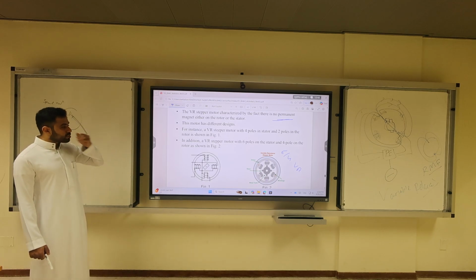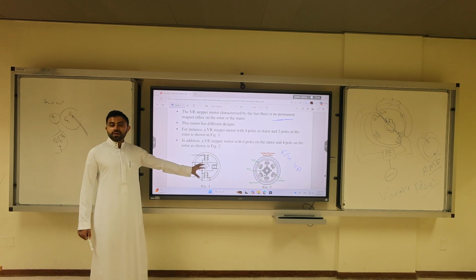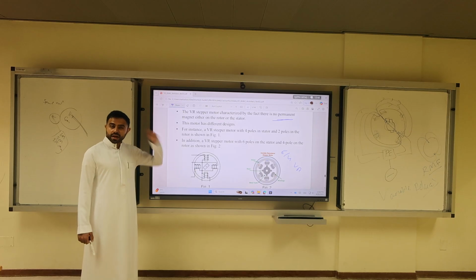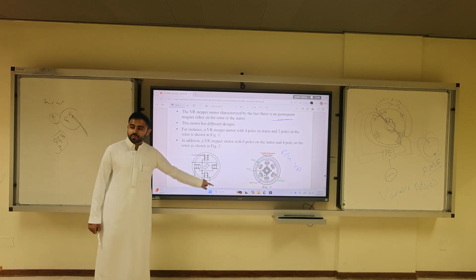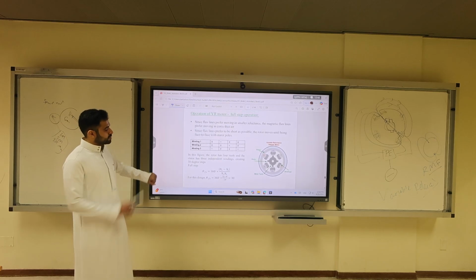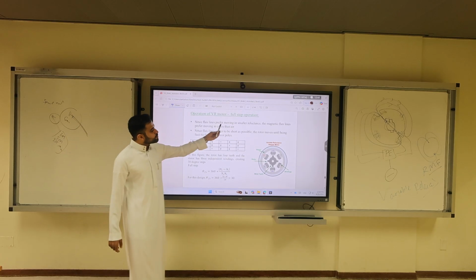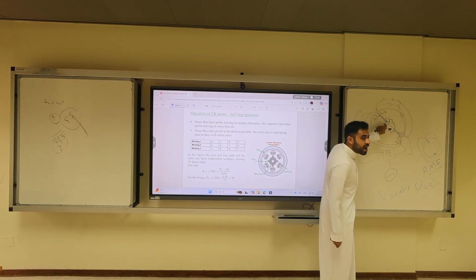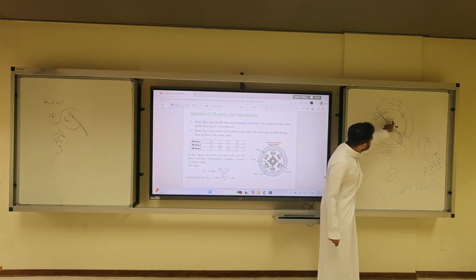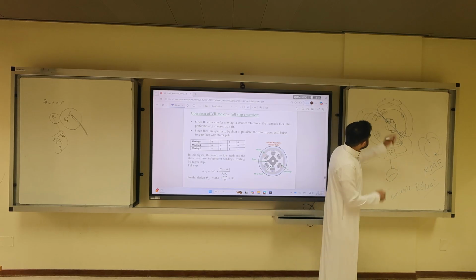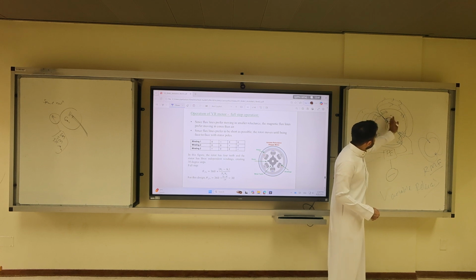It's very important to understand the geometry of them, because when you create the control tables for your machines, the number of rows will be based on the number of stator poles. How does it work? Well, this is very important. Flux lines prefer moving in a smaller reluctance. Flux lines do not like moving through the air. Flux lines would pull the head of this rotor here so that they can move in steel. The way it works is they would start moving here and over time they would shift it.